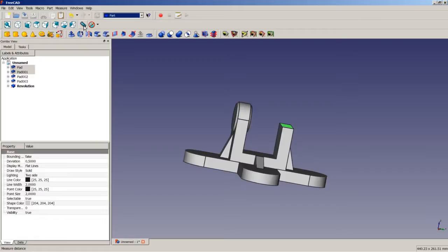You can use the measure tool here, which only measures between, generally speaking, 2 3D points. There is no possibility to select exactly an endpoint or to snap to a line or midpoint or something like that. You just measure from this point to this point in 3D space.